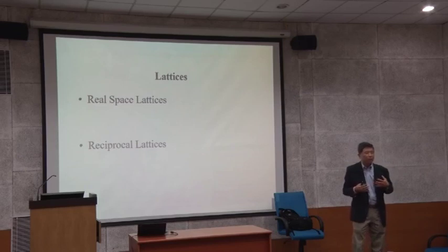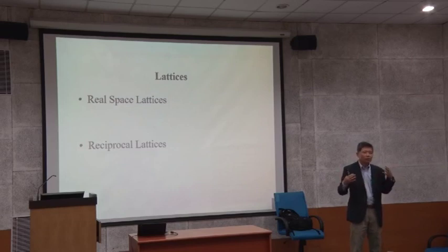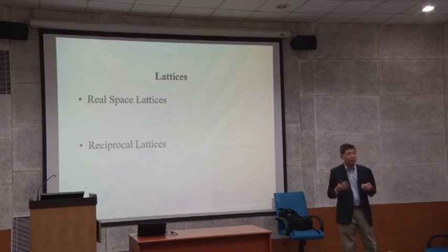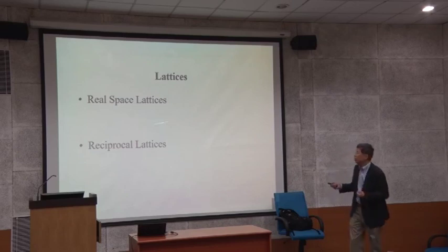And for most of the concepts you use in diffraction work, okay, real space imaging is good enough, most of the cases. But if you want to go beyond, to more complicated structural characterization, I think you have to understand the reciprocal space lattice, because the reciprocal lattice is much easier for understanding this. So I'll talk about these 2, real space and reciprocal space lattice.